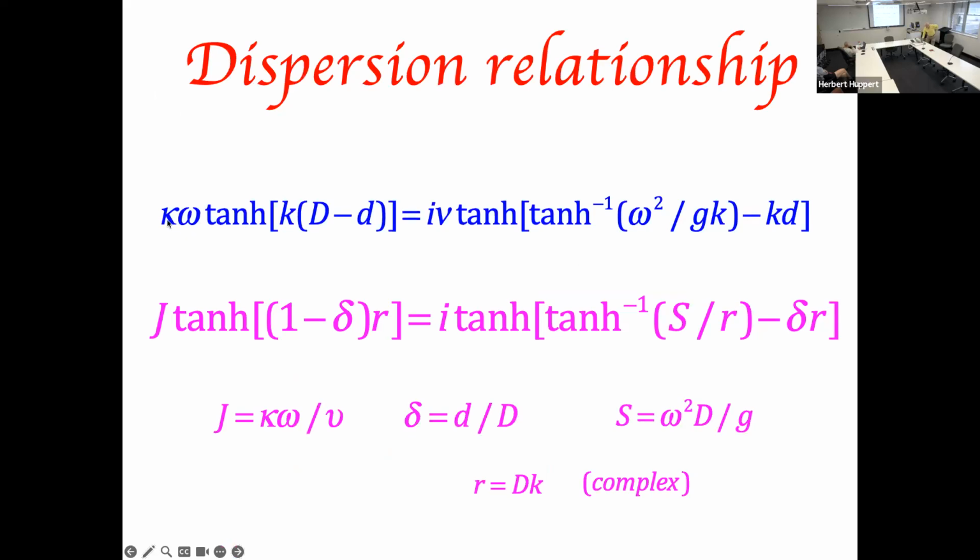If the permeability is zero, in other words, there's no real effect of the coral layer, then this left-hand side would be zero. That says that the right-hand side has to be zero for tan of something to be zero. That means the argument has to be zero, and we get omega squared equals gk tanh kd, which is exactly what we had before, though I've used little d for the depth.